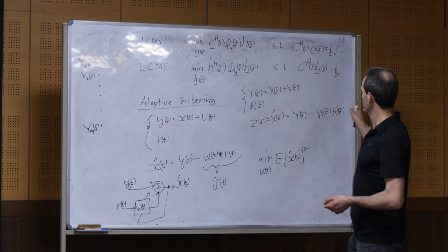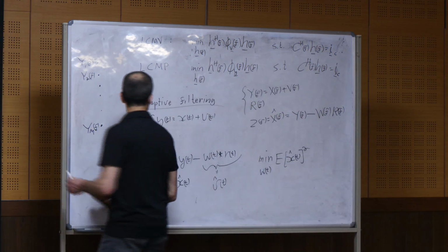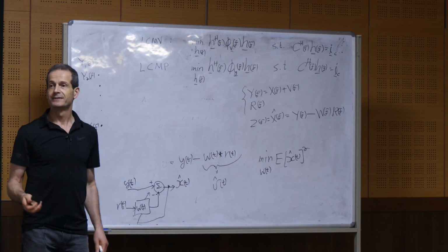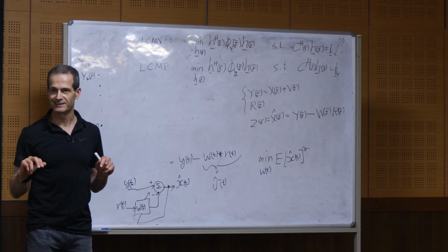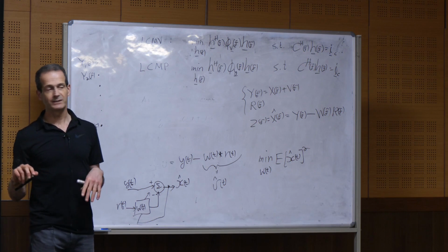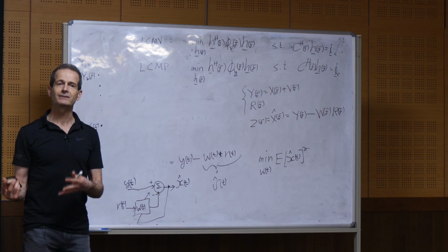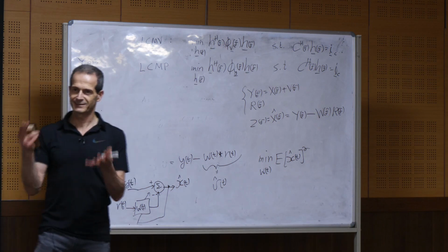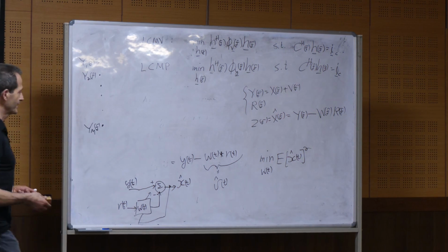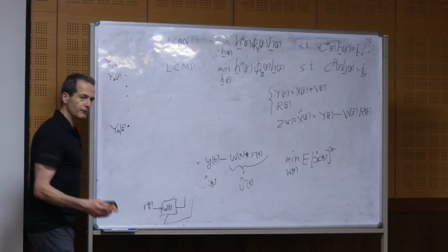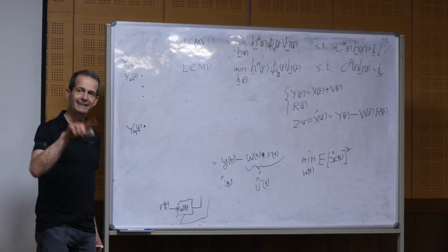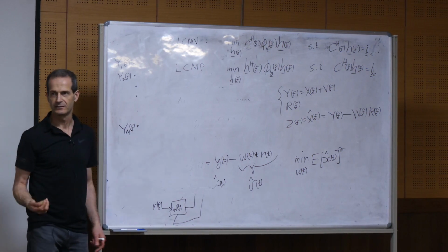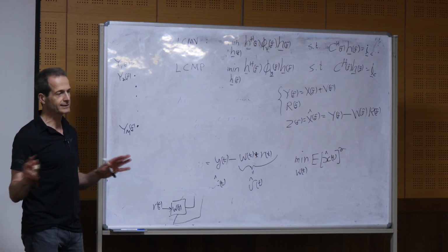So now we proceed as if we don't have what we sometimes call a clean reference channel, even though it's noise only. Because when we talk about a clean reference channel, we mean that it contains only noise. And if it contains the desired signal, we say it's not clean enough. This is the way we speak, because if we have the desired signal in the reference channel, it means that it has something that interferes with our filter. That's why a clean reference channel means that it contains only noise.